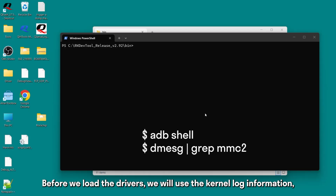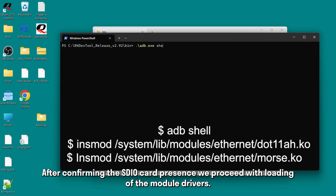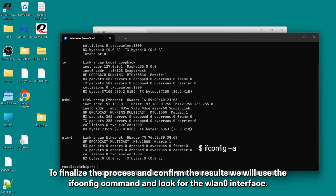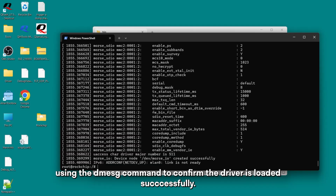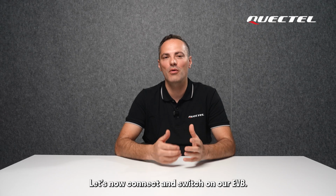Before we load the drivers, we will use the kernel log information to confirm that the SDIO card is present. After confirming the SDIO card presence, we proceed with loading of the module drivers. To finalize the process and confirm the results, we will use the ifconfig command and look for WLAN0 interface. If the interface is found, proceed with the final validation step, using the dmesg command to confirm the driver is loaded successfully. Let's now connect and switch on our EVB.